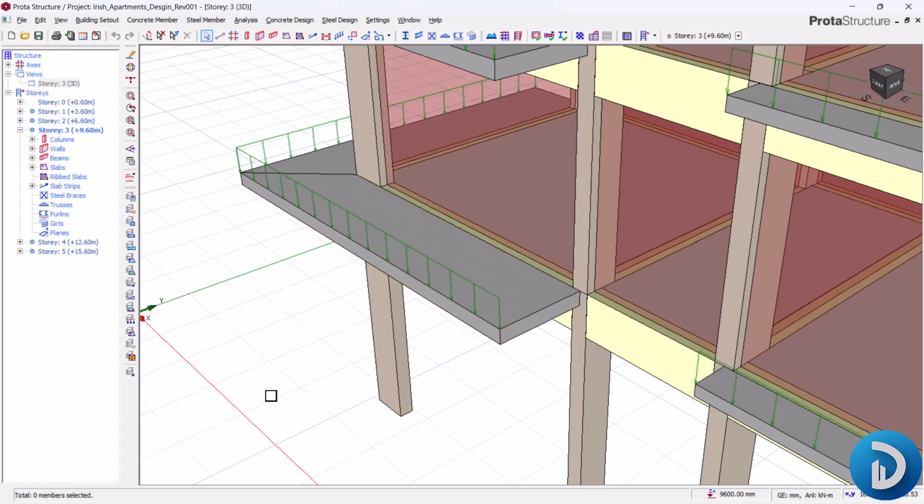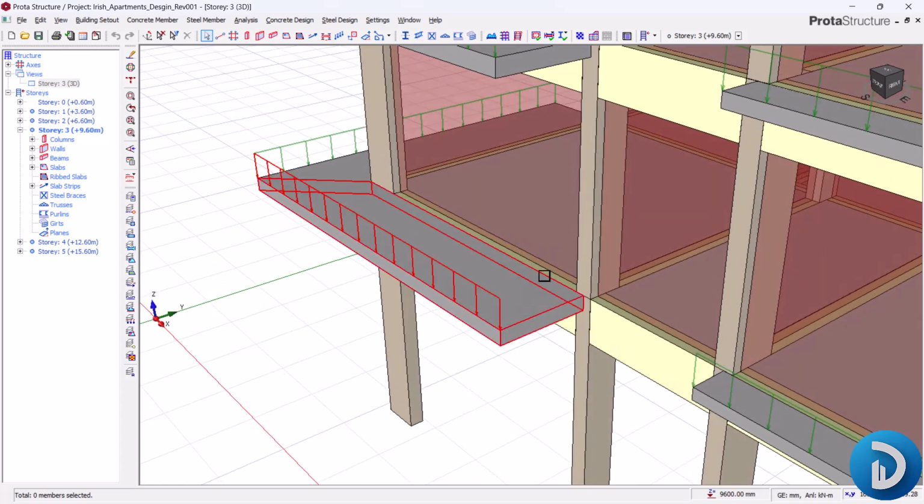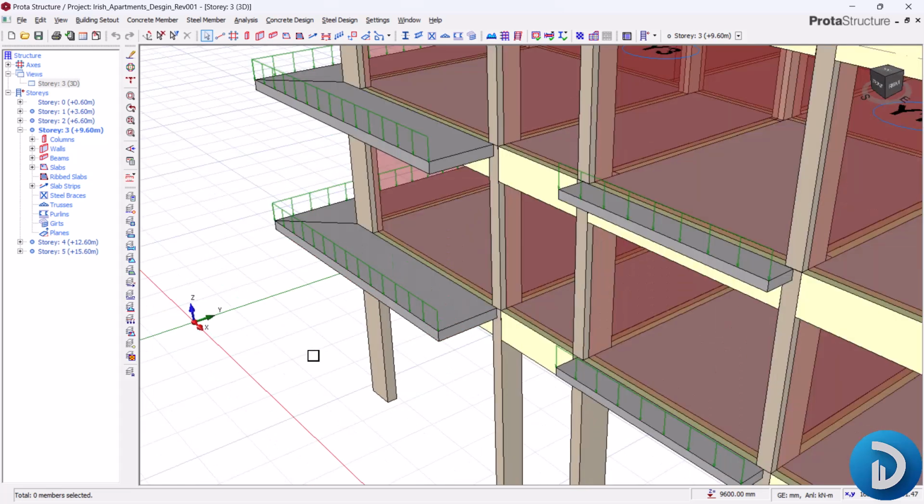Okay, so it means this beam is a critical beam and it has to be designed to resist this torsional moment. So we'll check the properties of this beam and check if the reinforcement that can counter this torsional effect has been provided. If it has not, then we can do this manually. So these are some of the modifications you have to make as a structural engineer, understanding structural behaviors and structural patterns.